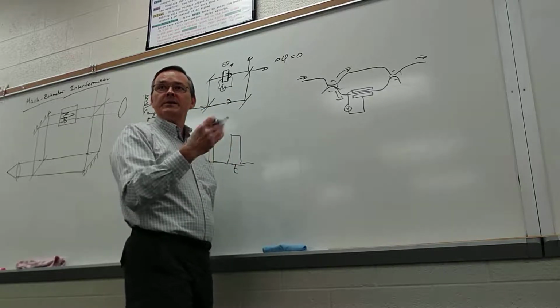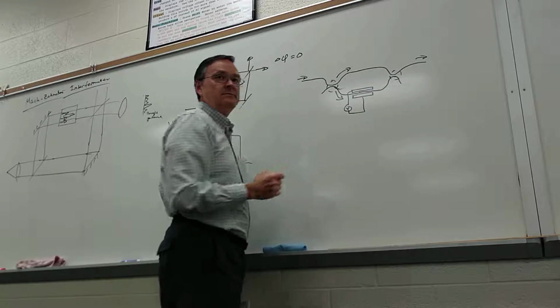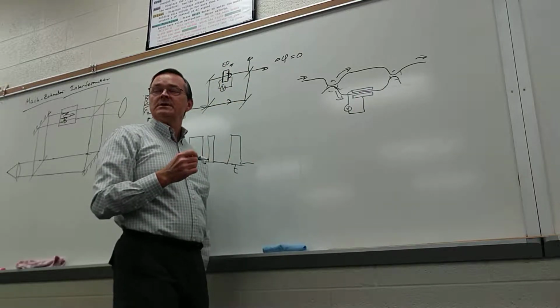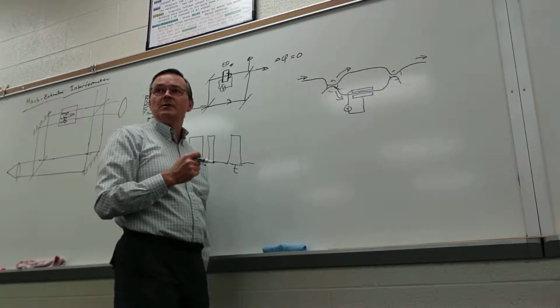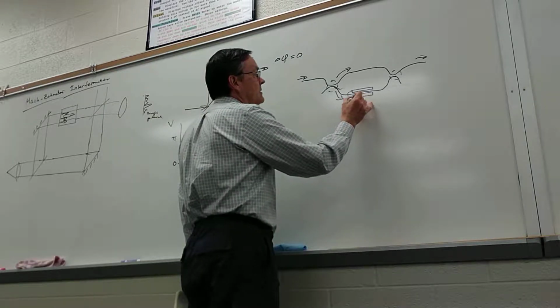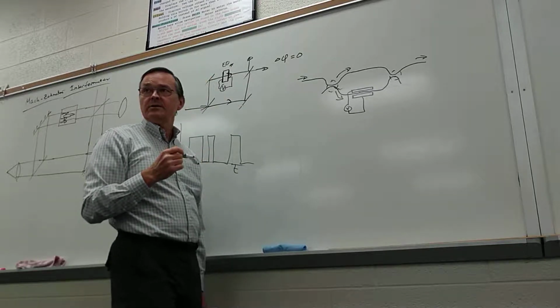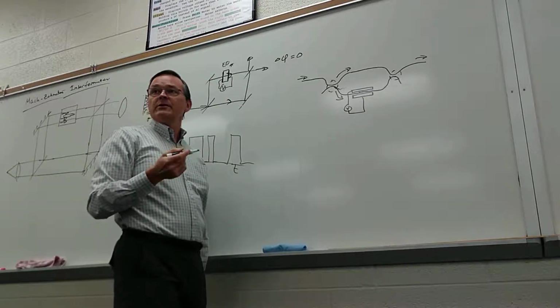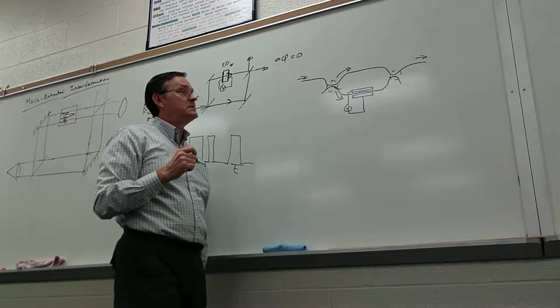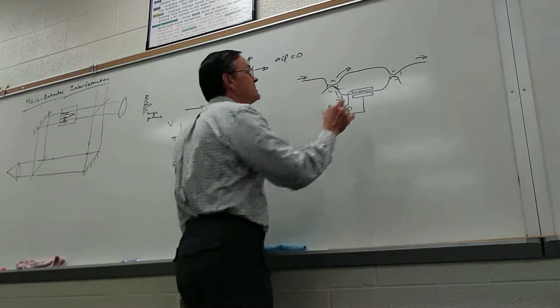And you want that propagation time to match propagation time of the light so that you don't have phase problems when you modulate. And then that means that the leads here you have to treat in the transmission line domain, and so you have to be really careful about the electrical design of that system.